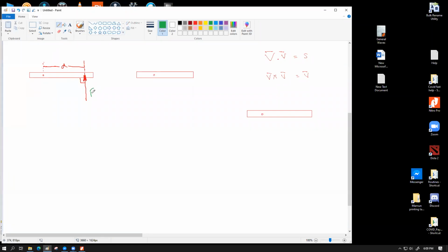So if we are applying a force over here and if there's 90 degree between them, then the moment is very simple. This would be force multiplied by distance, and that basically is the definition of moment. The reason we are not having any problem is because the distance and the force are already perpendicular to each other, which makes sense. What's going to happen if there is a bit of an angle between them? For example, let's say if this force in this position was not applied in that alignment, rather we applied the force in this alignment. For example, let's say in this alignment.